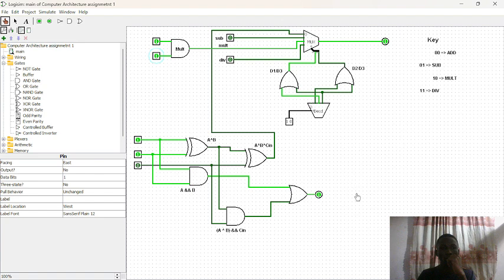You will understand at the end that the arithmetic and logic unit does addition with negative and positive numbers by just adding the 2 numbers together. So to get the negative number, you go through a procedure of first finding the sign magnitude, then you convert it to a 1's complement, then you convert it to a 2's complement to get the negative value of the decimal you want in binary. Then you add using the arithmetic and logic unit, which is the other circuit here. Now that's the addition for you. Then that's the subtraction.